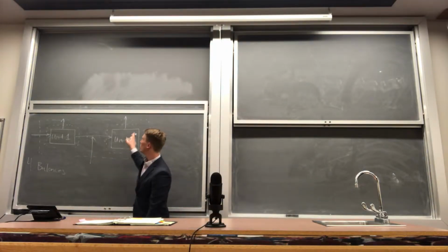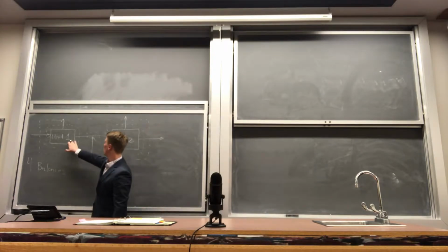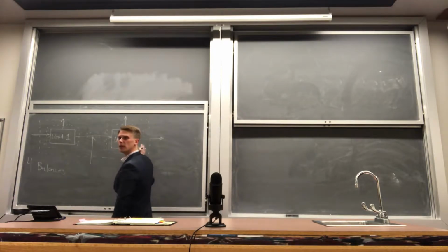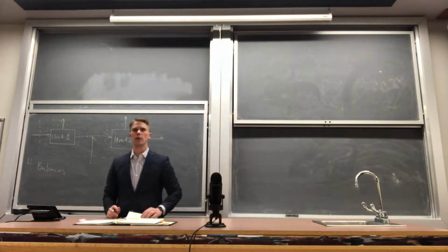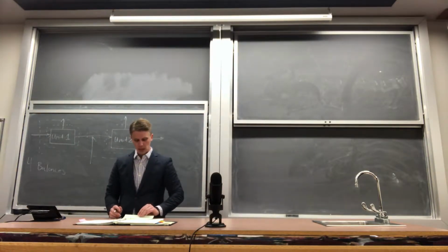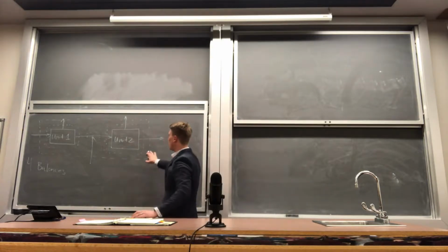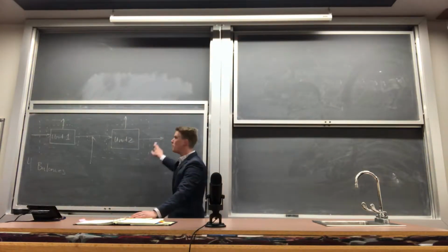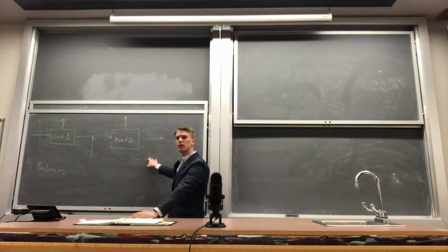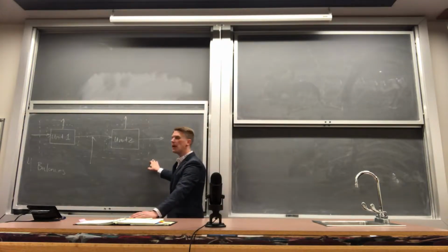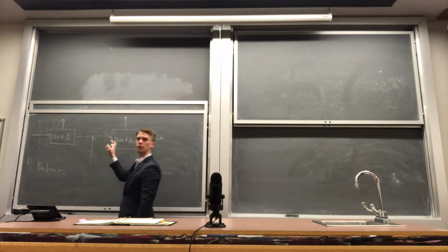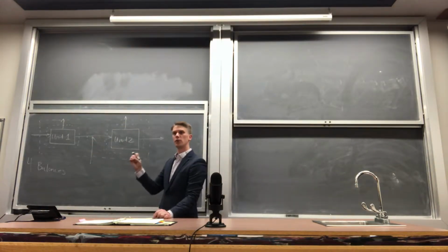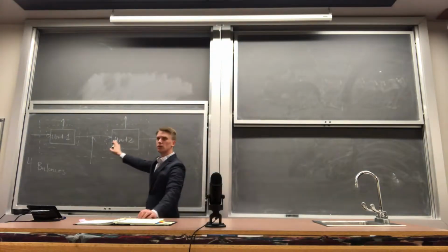In general, we typically would do each unit operation as its own balance and then a total, but there may be a situation where you can cleverly draw other balances looping around different parts of the process as well. So when we're working on a system with multiple balances, we need to start with each of these 4 balances that result in 0 degrees of freedom. We may not necessarily be able to solve unit 2 before we solve unit 1 or before we solve the mixer. Depending on what pieces of information were provided, it's not going to be crystal clear which balance to do.